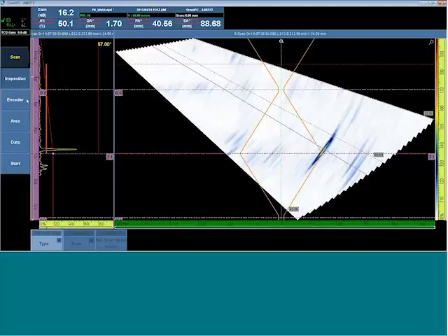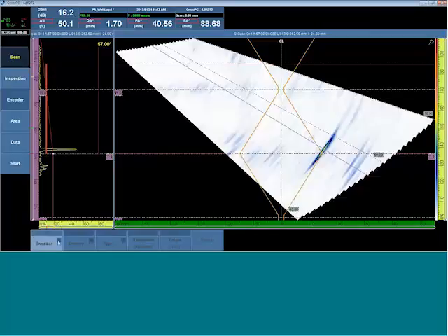The configuration of the hardware for the encoder is set here. So during our inspection, we have our scan axis on encoder 2. The OmniScan MX2 has a 2 encoder input through an IP66 connector. Depending on the wiring, your one-line axis might be on encoder 1 or 2, and in this case, it's 2. So encoder 2 is configured with the polarity, which tells us which direction the scanner is moving, forward or backward, negative or positive, and it can be changed at any time.